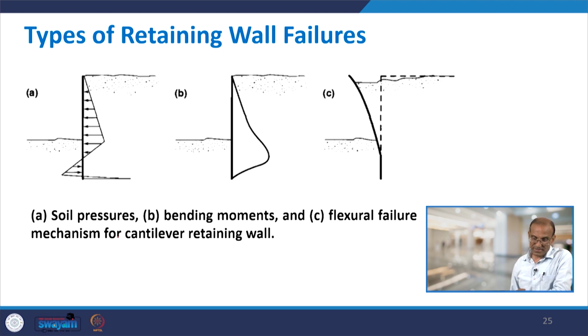In the soil pressure, and then you have bending moments here. So, this failure will take place due to the soil pressure. That means soil pressure exceeds the capacity of the wall. So, here the maximum soil pressure will be at this point. Then this is like on one direction compressive, on this side this is active and then passive. Here you have, so it may fail.